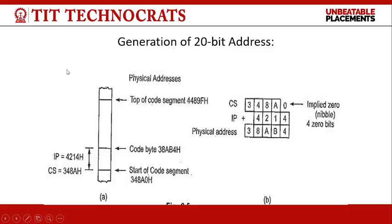Now, how the 20-bit address of the 8086 microprocessor is generated. Here the diagram shows the process of 20-bit address generation. The content of the code segment register is multiplied by 16, that is, shifted by 4 positions to the left by inserting 4 zero bits. This is done in a shifter, and then the offset, that is the content of the IP register, is added to the shifted content of the code segment to generate the physical address. This is shown in the figure.